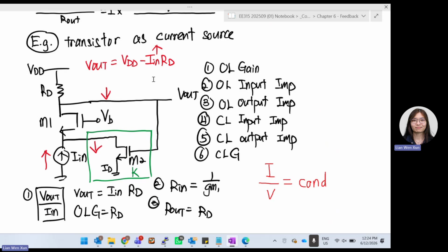So the question goes back to transistor. Remember, our MOSFET is a voltage to current converter. So we go back to transistor. We can just use only one transistor. My transistor, the MOS, the gate connects to output, so I can measure the output voltage already. I measure voltage, but my transistor gives output as a current. So this current drain I connect to somewhere, then I already feedback as a voltage to current converter. So let's find one by one.